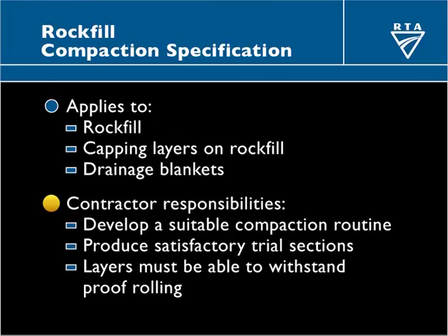As I've said, you need to develop a suitable routine. It's got to produce satisfactory trial sections, at least 2, and it must be able to withstand proof rolling.